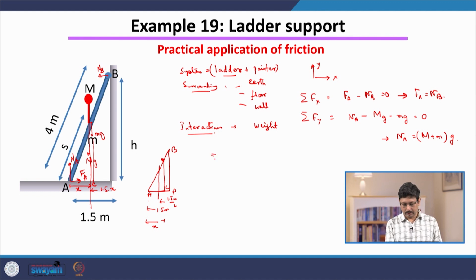So, let us say M B. What is the torque due to the force A? This is effectively a 2D problem, so the moment of force or torque is very simple. It is just the perpendicular distance between the line of action and the point B, times the magnitude of the force, and the direction of the torque is perpendicular to the screen, either going upwards or going downwards. That you can determine from the right hand thumb rule.